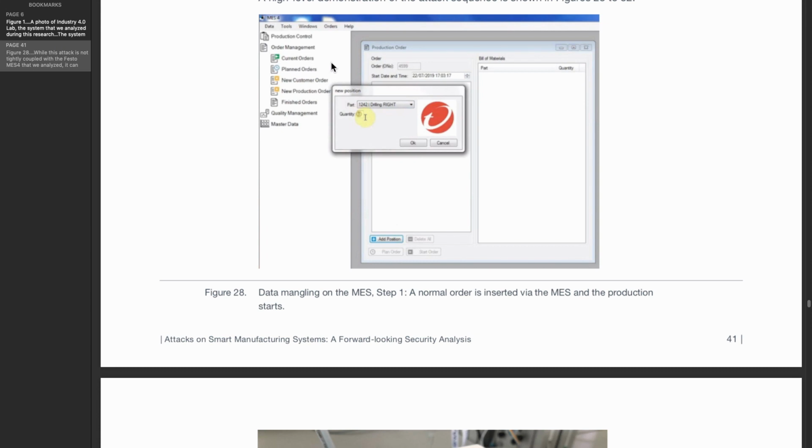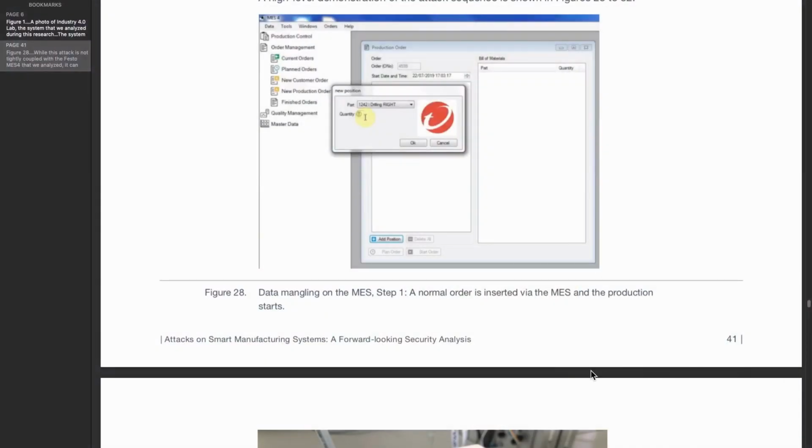So every production order is a series of steps that each of the components, such as a PLC and the machines, have to go through. And the MES makes sure that all the parts, all the components of the system receive the order at the right timing, and that there are enough resources in the loaders of the parts, for example. And it keeps this aligned with the database of the ERP, Enterprise Resource Planning. So if there are any supplies to order, the MES will notify the ERP, and then somebody will take action, right? So let's go back again to the paper.